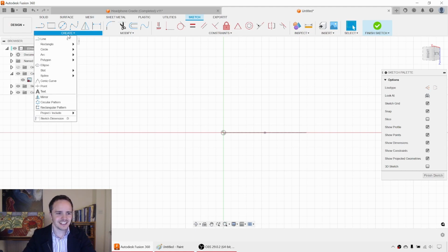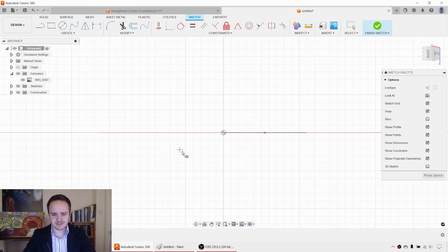It's going to make sense. We'll start off by making an ellipse. And this ellipse I'm just going to draw arbitrarily, but it's going to be 30 millimeters wide. Again, ellipse, 30 millimeters wide, and then hit tab. Make sure it's upright, and 10 millimeters tall. Good stuff. And now it's floating around in space.